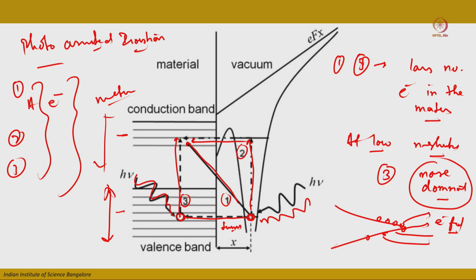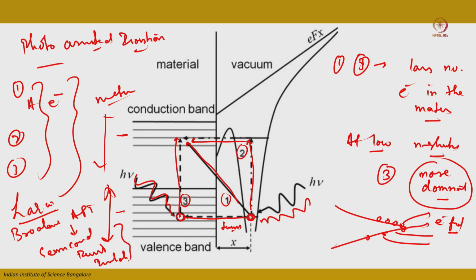So the laser pulse, which uses these three phenomena, broadens the application of APT towards semiconductors, functional materials, and also in some cases insulators, where the HV pulsing method is very limited in use and the yield is very low. So these are the three phenomena by which the photo assisted ionization of the adsorbed atoms can take place.